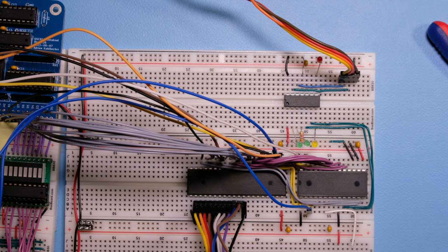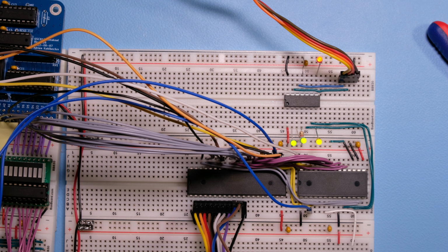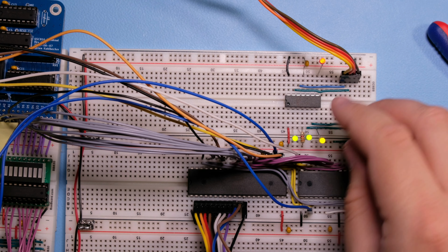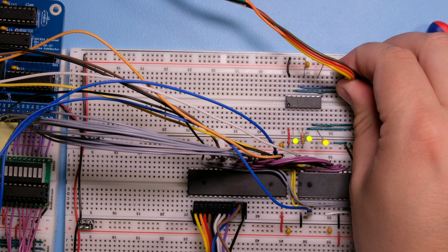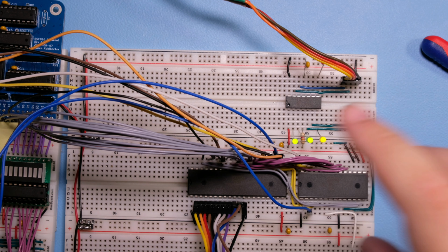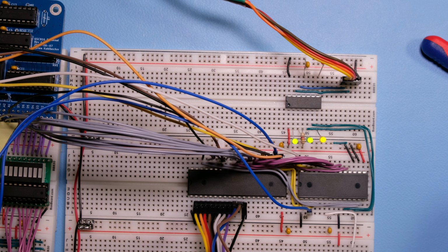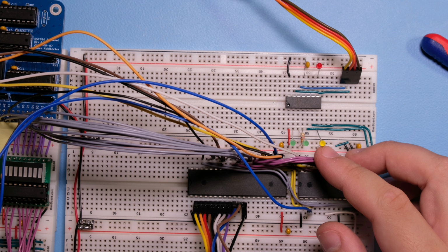Let me plug the USB cable to my computer and see what happens. Yeah, of course, because the computer is not powered. So let me turn on the power to the computer. I'm seeing something on the configuration here. Nothing is happening. Also, I think I have the LEDs reversed. Okay, so yeah, so all the signals are active low by default, which is why the LEDs are all lit up now. So let me just reverse them. Okay, so we should see the orange LED light up when the device is configured.